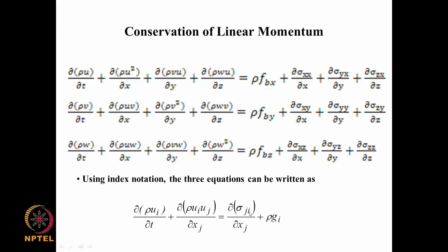So, for example, when you put i equal to 1, this has to be x here, the corresponding x component in x component. So, that i identity is maintained throughout here, but whether it is j or k, it does not matter because it is anyway going to change x, y, z like this. So, the j here is a dummy index and i is a proper index with substance attached to it. So, sometimes for convenience we put it as dou by dou x m of rho u m u i, it is the same as dou by dou x j of rho u j u i. Okay.